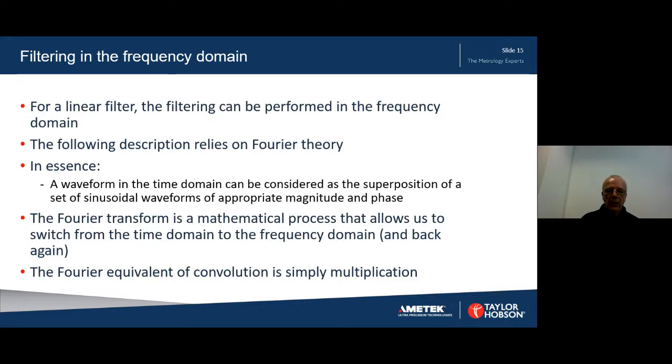The desire to use the frequency domain comes from the fact that the filter transmission response is defined in frequency terms. Once we have moved into the frequency domain, all that is necessary is to multiply each frequency amplitude by the transmission of the filter at that frequency, and the resulting data set will be the filtered frequency domain signal. Taking an inverse Fourier transform will then yield the filtered time domain signal.